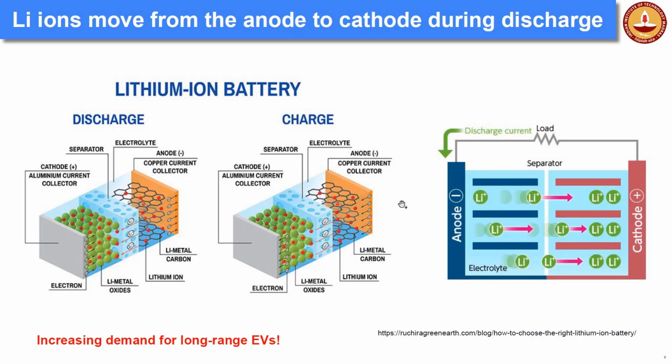So what does this suggest? This is something that is a high potential thing. That is, it is not a spontaneous process, rather a non-spontaneous process. That's the reason you are giving some energy to push the lithium atoms that are present in the cathode material to move towards the anode material through this particular separator. Okay, so here in between, whatever we are seeing, there will be some electrolyte like ethylene carbonate, propylene carbonate and so on. They are just solvent molecules essentially, through which this lithium ion will be traveling and it will be reaching the other end, where you have the anode, which is graphite.